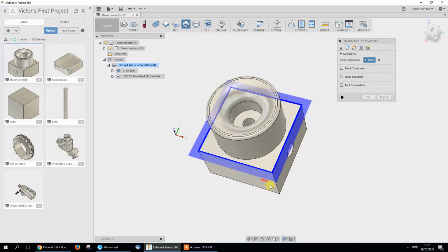In this case, there's a red arrow where you can select if we cut from the outside or the inside. If we cut from the inside, it's going to remove the circle. So we need to cut from the outside. Or let's try something. Forget the square. Put the circle. Sorry about that. The blue area is the material that is going to be removed until that height.